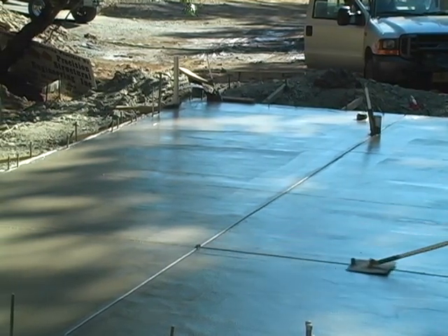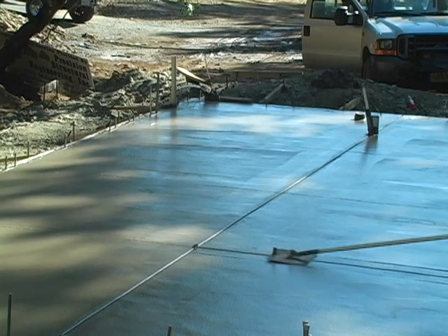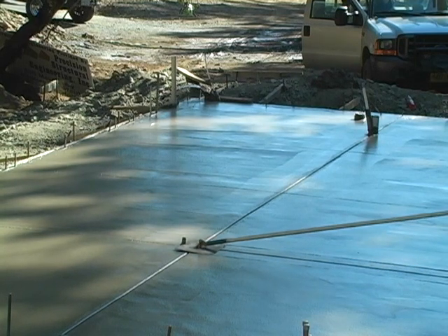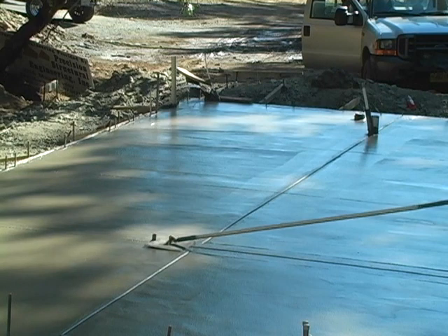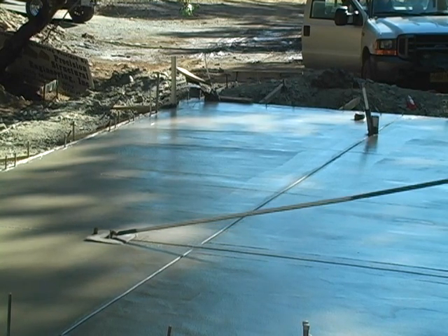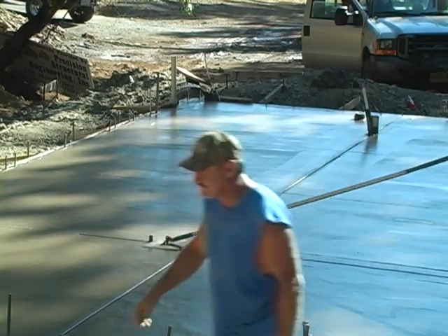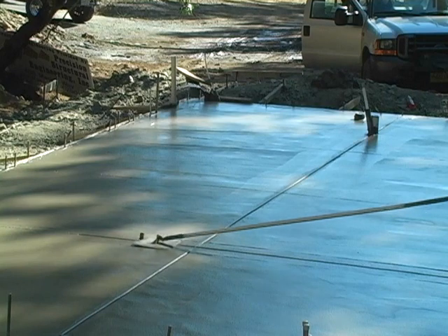And you can see right there in the center where we meet that perpendicular line that it actually creates a little bit of a blob of concrete in that line. That's pretty much impossible to get rid of. What we want to do is push all the way through here, and we'll move most of it out, but it will push a little bit of concrete into the perpendicular line. So one way we can do this is wait for things to firm up just a little bit so we can get on there onto the concrete with our knee boards.